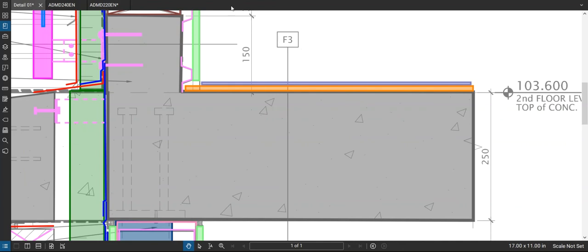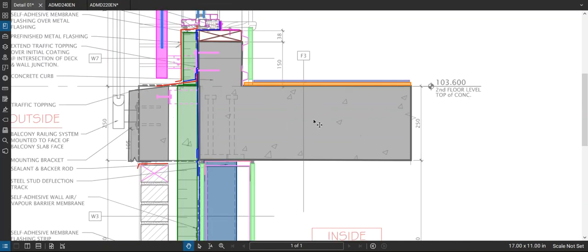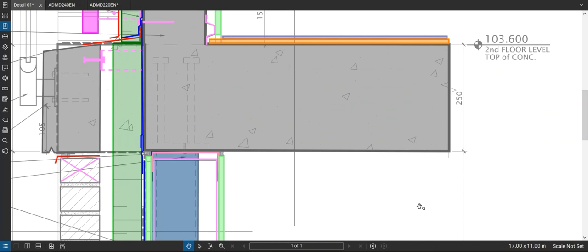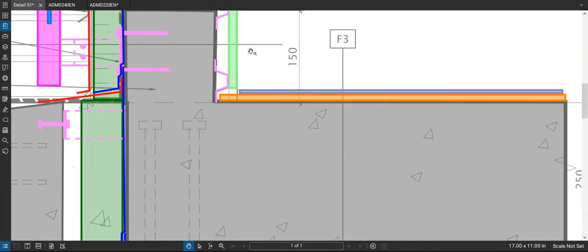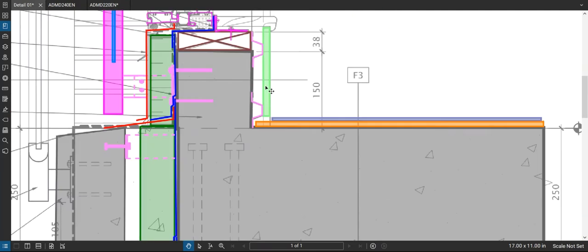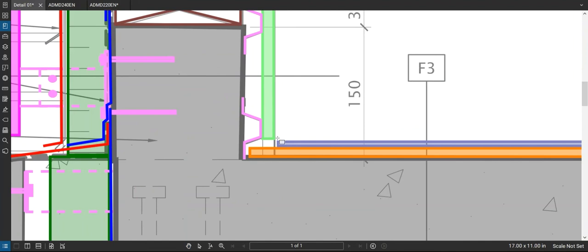the impact sound transmission. And then that becomes a whole topic of its own because then you can put a drop ceiling in there and you could have resilient channels on the ceiling. You could have hangers that are like resilient channels. There's all kinds of stuff from an acoustic standpoint. So again, I'm just showing the bare minimum. I'm not going to get into that in this video, but there's all kinds of considerations to think about right there. And of course, here you'd also have probably a baseboard to finish that off.